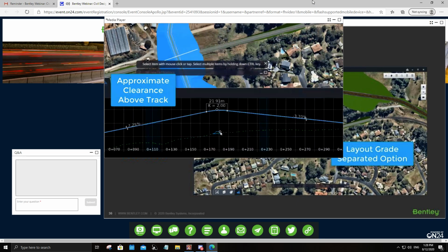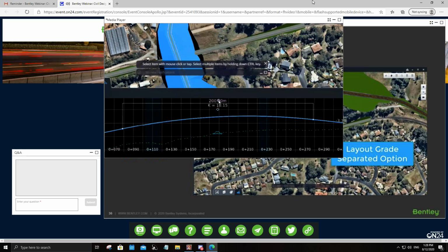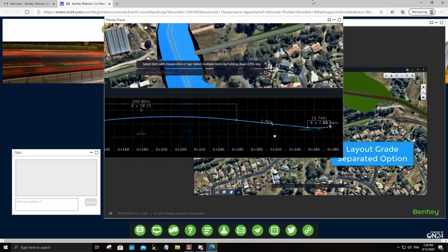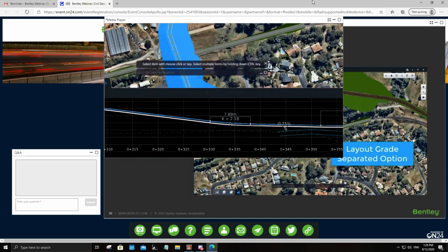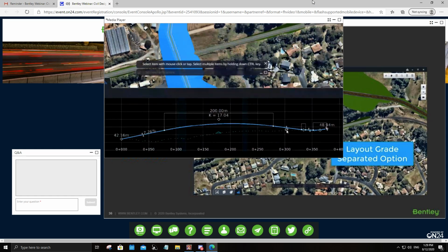It's just that we cannot add any more rail specific objects. So adjusting the vertical profile of Mackay Road option 2, we will make sure that it's high enough for a bridge to be designed in this location, and that we are tying in nicely to the existing ground and existing roads.